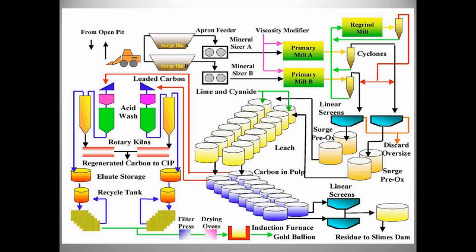They're sometimes difficult to align, but a failure of either one of these rotary kilns in this process cuts their production line in half, cuts their process output in half. So it could have a huge effect. Or if we move over to some of the other ones, maybe the primary mills or one of these other cyclones, maybe there's capacity there that we can run the whole process with one of those being down. So it makes one of those a little less critical.